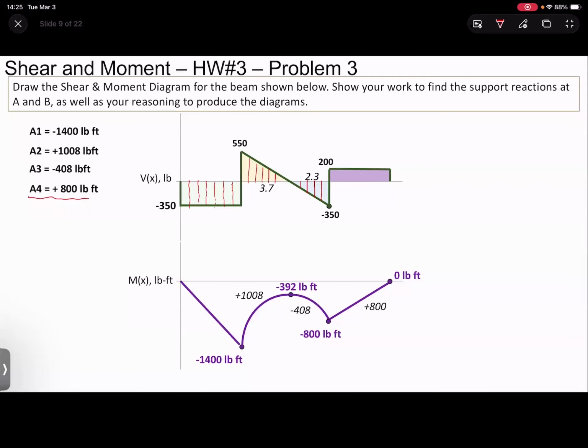Now, this is what I asked you to solve, but for this, where would the max be, right? Max right here would be this 1,400 pounds. This would be obviously our max produced here. And the location of that, again, you can always see the maximum or the minimum of the moments are where the shear is equal to 0, right? So you can even see in here, this is an inflection point because the shear is equal to 0.